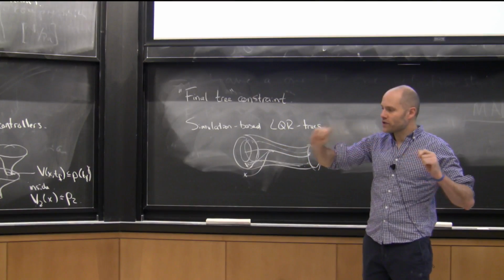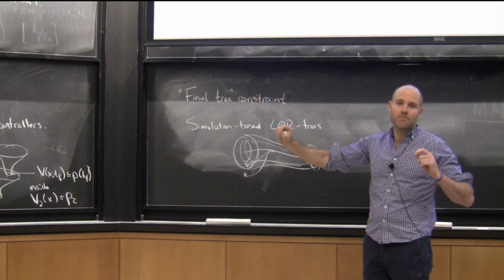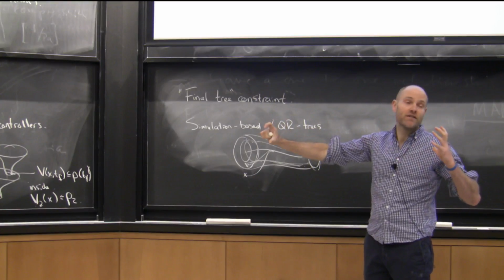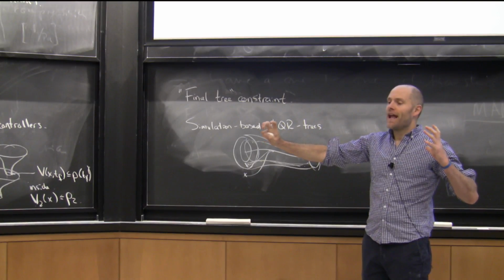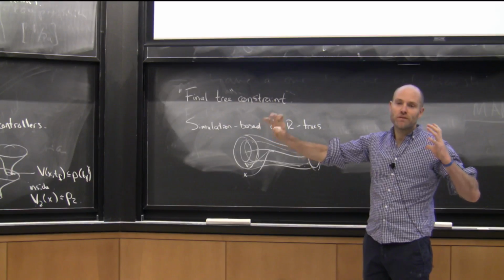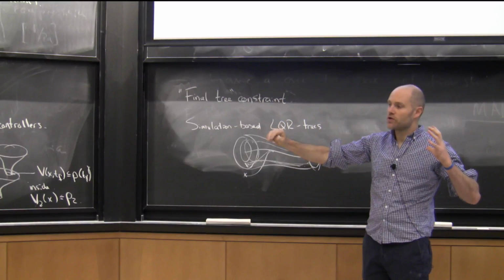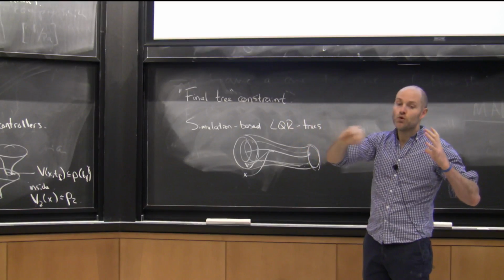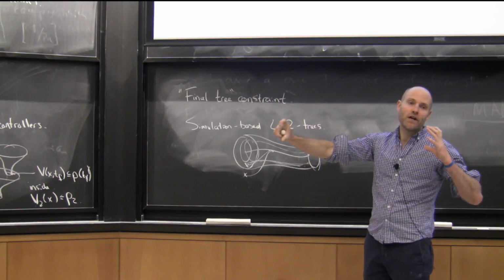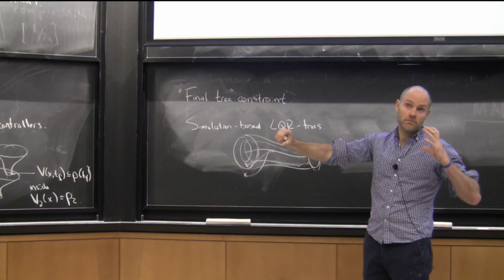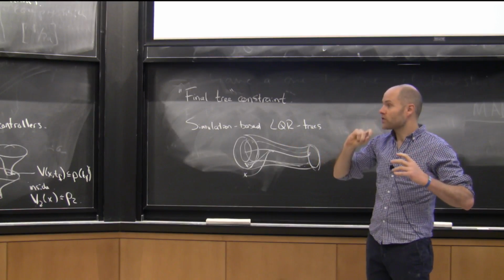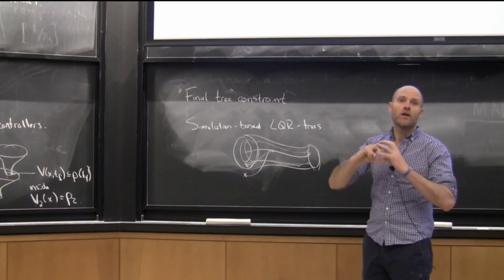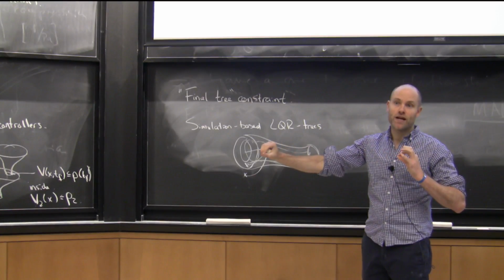Even if you use a trajectory which may not be realizable with the real model, you can use that to compute a region in state space, and then ask, will that region still be valid if the model was wrong? So the trajectory sort of disappeared from inside. The trajectory might have had to move, but you can still ask, is this an invariant set for my uncertain system? So you can ask fundamental questions about robustness and uncertainty when you're thinking about regions that you couldn't have asked when you're thinking about trajectories.